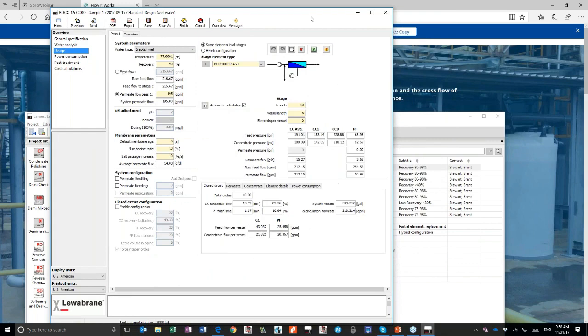Oh, great. Okay, and actually we have another one coming through here that is related. How is the maximum recovery determined with regard to anti-scaling? Using CCRO, a higher percent saturation can be achieved for any given anti-scalant. For instance, if a product limit for calcium sulfate may be 300% saturation concentration for conventional RO, with CCRO is there some higher limit, like 400 or even 500, and how is that determined?